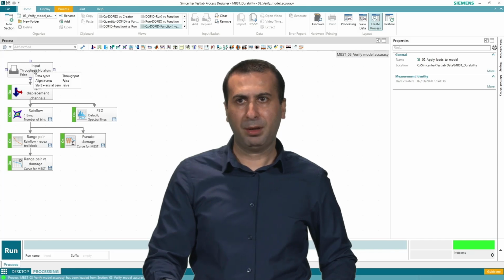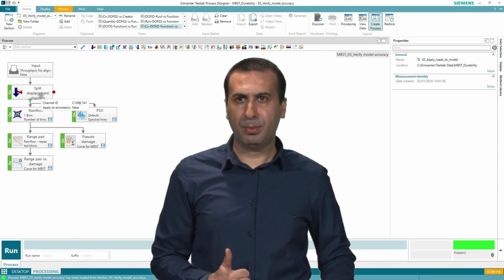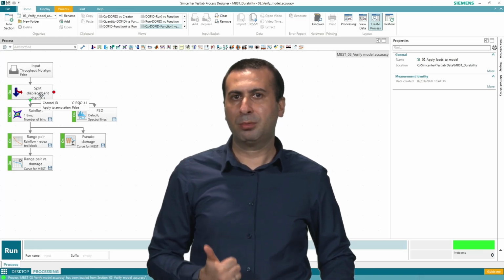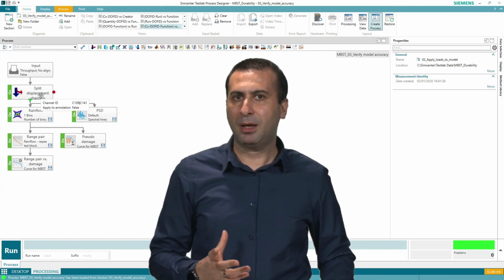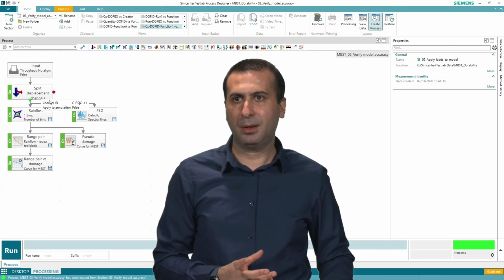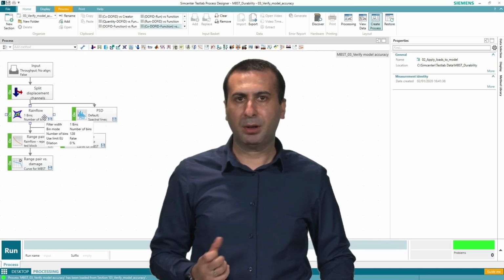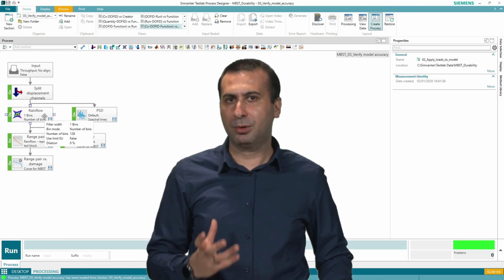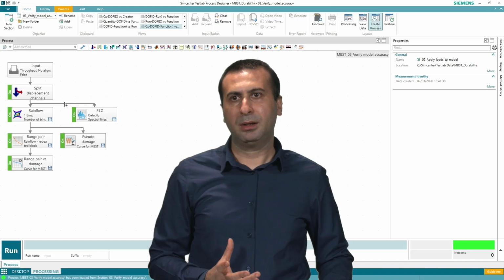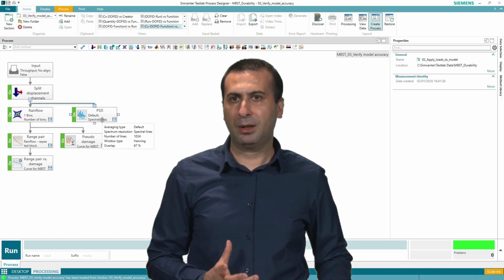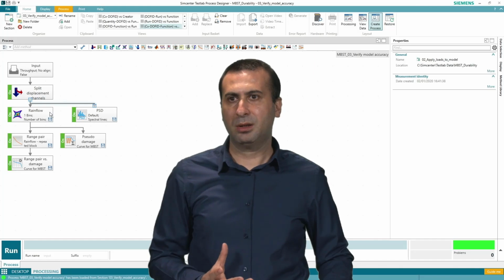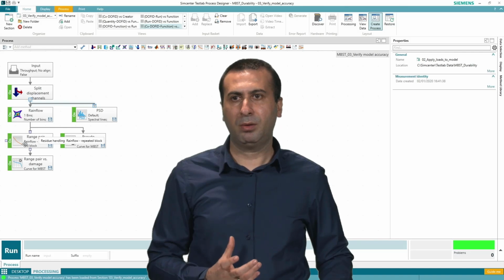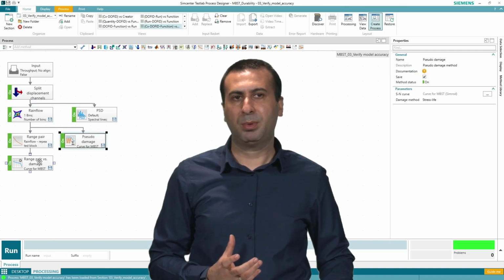So all the runs will come here. I will only take the shock absorber displacement channels because these were the channels I could measure and simulate. So it will already give me an idea about the accuracy of the model. Then I will calculate rainflow counting over these displacement channels, again in order to classify them based on the amplitude ranges and the repetition. Then another flow will go over there in order to calculate the PSD between these different displacement channels. Then over rainflow, I will calculate the same as I did before: range pair, pseudo damage, and range pair versus damage.